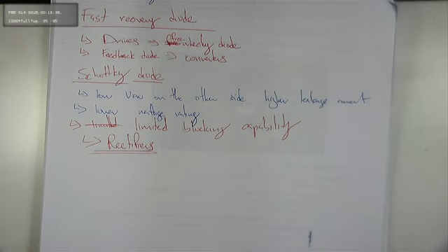So if your diode is rated to handle 10 amps of current, what will be the rating of your fuse? Something less than 10? Yes, so that it does not blow up your diode. So make sure you take note of this.